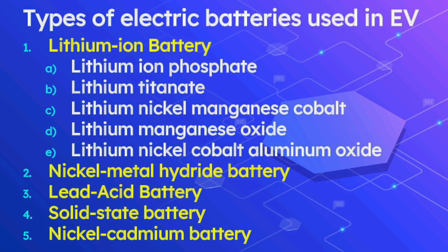Before choosing the type of battery, there are some important points to be considered which affect battery performance. Coming to the first point, specific energy. This defines the battery capacity in weight, Wh per kg. The capacity relates to the runtime. Products requiring long runtimes at moderate load rate are optimized for a high specific energy. Second one, specific power. It is the ability to deliver high current and indicates loading capability. Batteries for power tools are made for high specific power and come with a reduced specific energy.